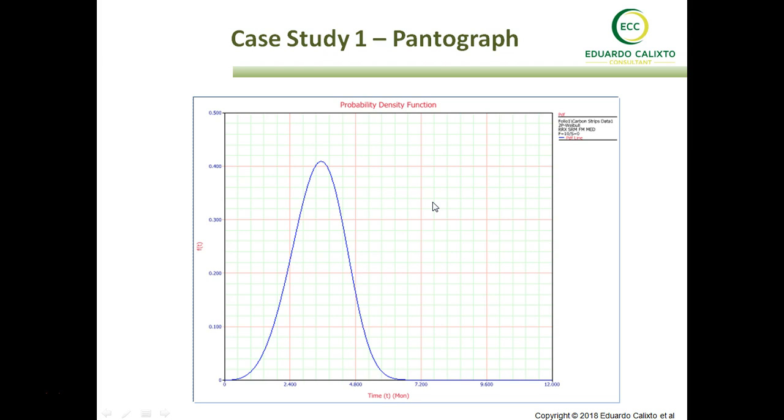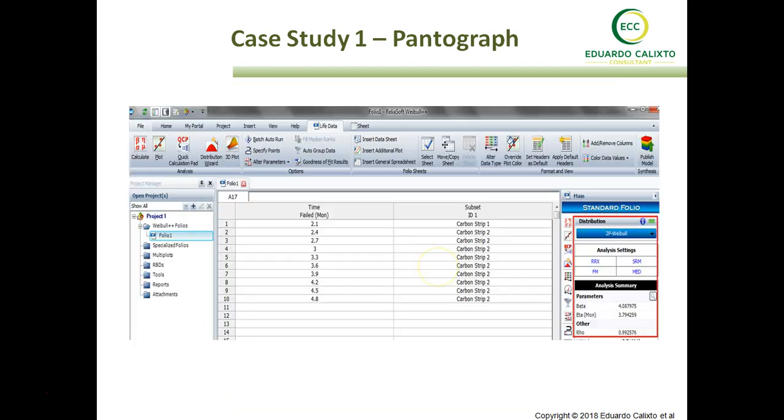So when you look at the Weibull parameters, let's just come back here. You see that the beta value is very high. It's higher than 2.5. So in this case, we have something similar to a normal distribution. Remember that the Weibull is a generic PDF, and because of that, in this case, it will represent a normal PDF when the value is between 2.5 and 4. And the higher this beta value gets, it starts to become closer to a Gumbel PDF.